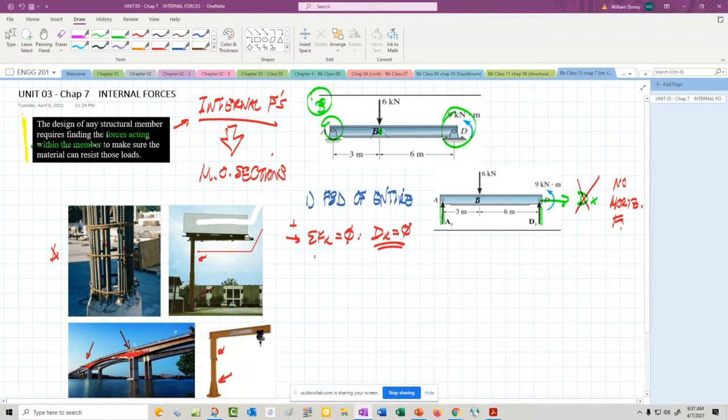All right, some forces in the y direction. See what's happening there, positive up. We'll have Ay minus 6 plus Dy equals 0. Can't really do anything with that, so we have to go to our last, which is sum moments.